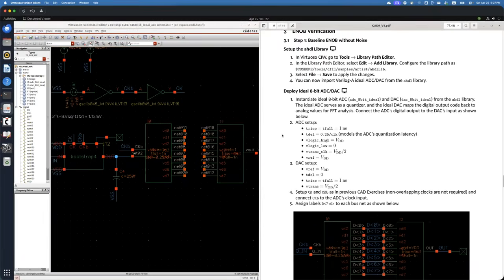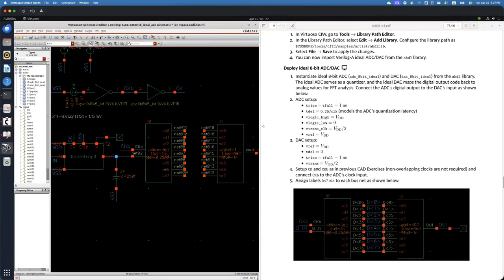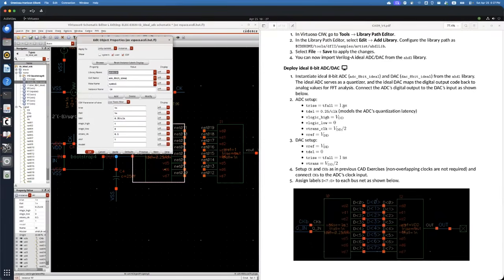So for the ADC setup, we can set it like this. For example, rise time and fall time, just 1 nanosec as a very good starting point. You can of course set it as 1 picosec, that is fine. But 1 microsec is sometimes a bit challenging to model the real environment. So what I typically suggest is to just set it as 1 nanosec.